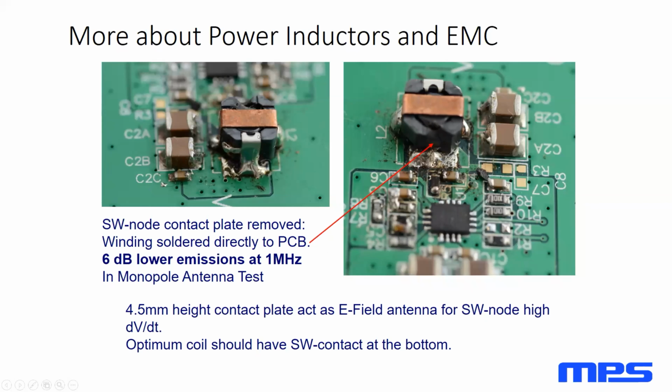So this clip is acting as an effective antenna. And I mentioned previously, we had looked at rotating output capacitors around by the inductor. What we were trying to do there was to create those tall buildings, so to speak, where we would have this ground connection where that radiating antenna could be blocked by the capacitors. So that's one thing that we tried doing in that particular case, and something that you can do. Try and block this antenna from being effective at all in terms of bypassing any amount of filtering or having energy go somewhere we don't want it to go.